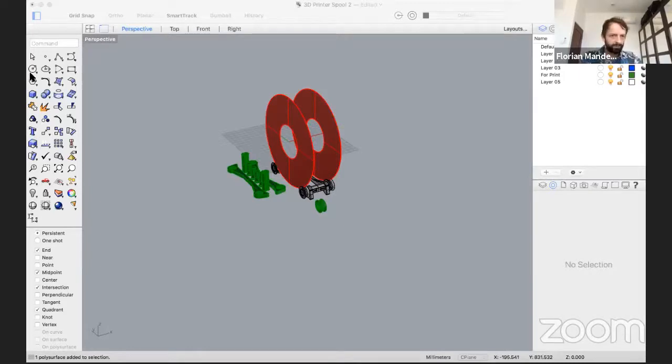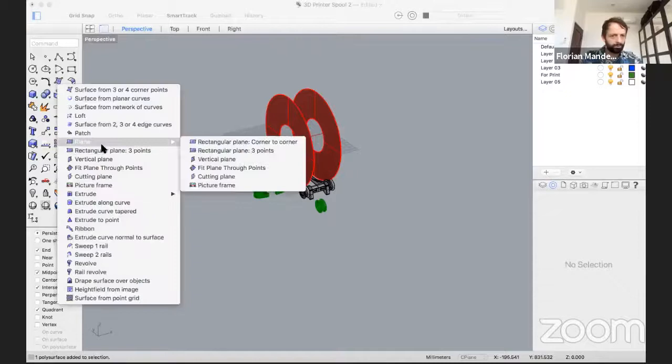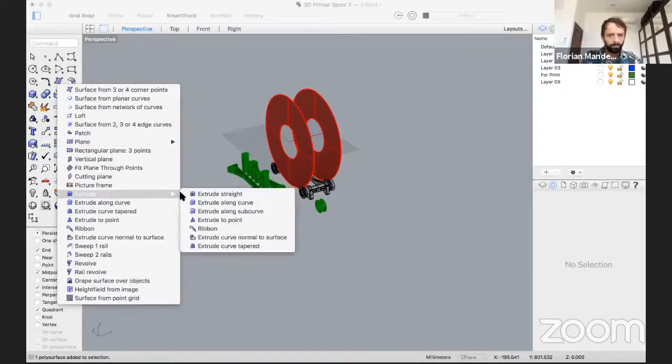So if I'm drawing a circle here, from the front view and the right view, I don't see anything. I just see a black line. But from the top, I see how it's round. From the perspective, I can navigate around with a mouse, and I can see the circle in 3D. Then what I would do next is extrude it.